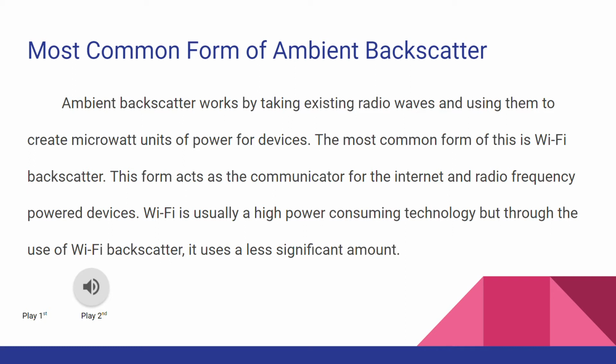The most up-and-coming form of ambient backscatter is Wi-Fi backscatter. Typically, the use of Wi-Fi can be very draining on a battery. Instead of automatically using the Wi-Fi signals produced by the router, the Wi-Fi backscatter devices encode the data by choosing to use or not to use the signals. This results in changes to the signal strength that can be detected by devices such as smartphones, laptops, and even routers. Through the use of reflecting the signals in this manner, we can communicate with devices using significantly less power.